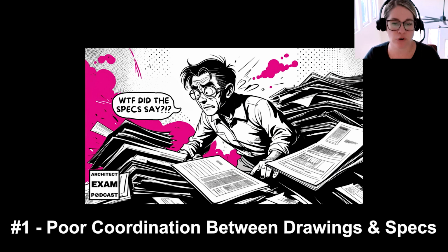My favorite way to cross-reference drawings and specifications is to create a simple spreadsheet with two columns: one listing out the drawing and one listing out the corresponding specification section. Use this as a checklist before issuing documents. It takes a bit of time up front, but it saves a lot of time and a lot of headache later.